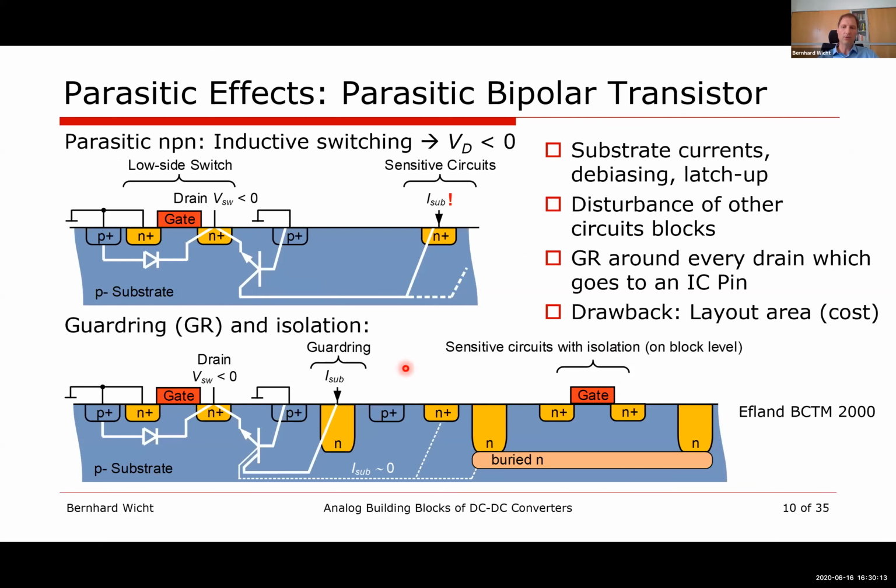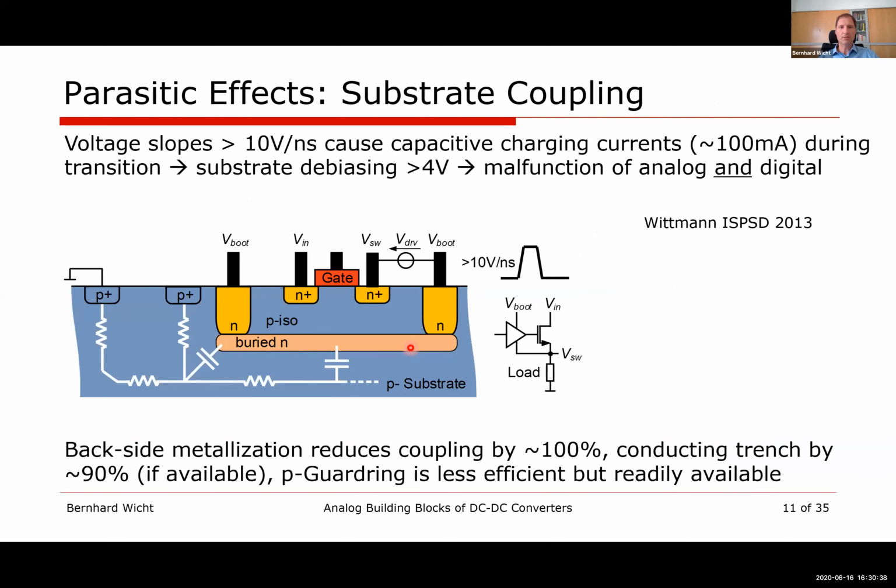So I would always go for SOI. And in fact, there are a lot of reasons that it may even pay off cost-wise, because you have your bipolar parasitics better under control, and also in terms of silicon area, since you can squeeze down some power stages and so on. So it actually looks quite good. Is that okay for you? Yeah, I'm okay. Yes, thanks. All right, you're welcome.